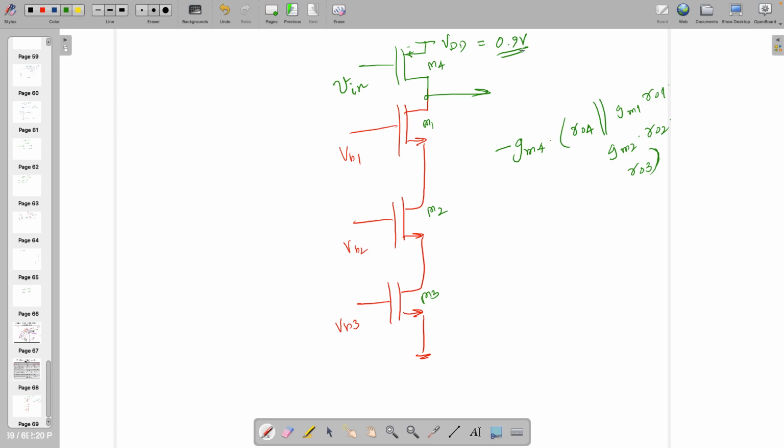How do you know that it's not sufficient? Because there are 4 transistors and minimum is 250. So 250, it goes beyond 1 volt, right? Because 250 is the least value. It's not the value from where it starts. Sometimes some of the transistors will automatically take charge at 400 millivolt or maybe 500 millivolt, or depends. So headroom has to be more than 1 volt.